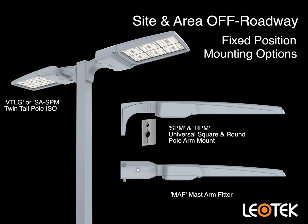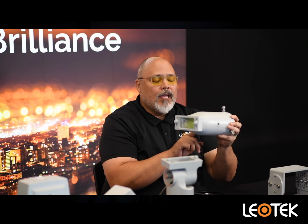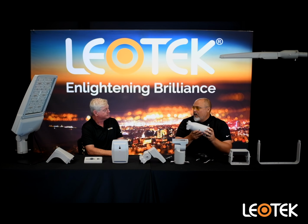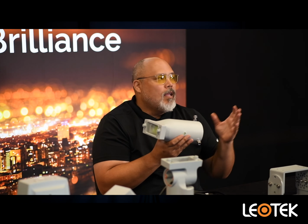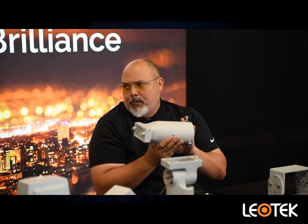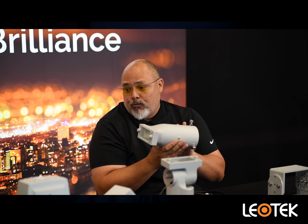One little detail that I forgot to mention on the Mast arm mount and the slip fitter mount, it comes with a through bolt hole that you can see here. So think about if it's on a pole horizontal and you're a little bit concerned about vibration over time and the fixture, you may be concerned that it may fall. That through bolt gives that little bit of extra security if the installing contractor wants to install that through bolt.